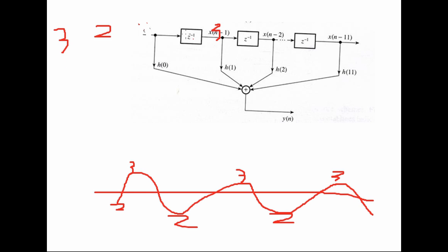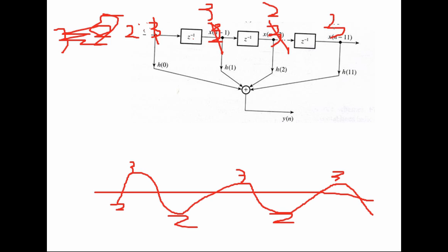So this 2 must move over to this side, and the 3 that was here will move over to that side, only keeping the 3 that is there now. So when the next 2 comes in, this 3 will move there, that 3 will move, that 2 will move there, and that 3 will move there, filling up this shift register. So this is what you normally call a serial in, parallel out type of processor. It depends on what processor or language you program in.